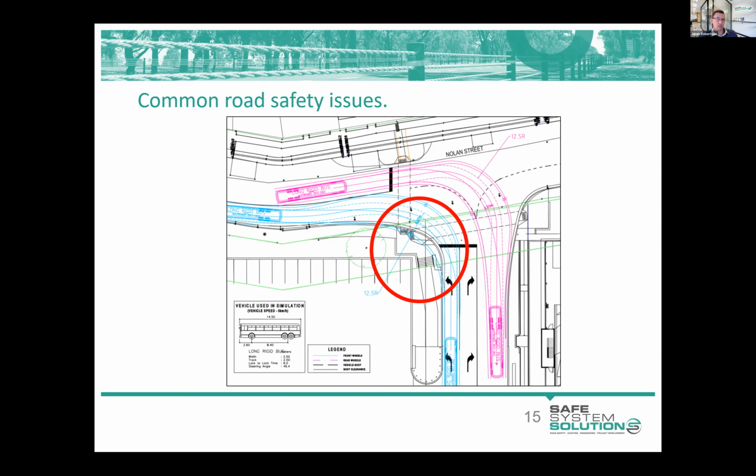It's important to understand the full extents of the vehicle envelope or swept path, and usually that's the front and rear corner of the vehicle. Other lines shown here are the dashed lines, which represent the wheel paths. There's also often a line along the centre of the vehicle. And then at the outside of the swept path, you can see two parallel lines on each side.